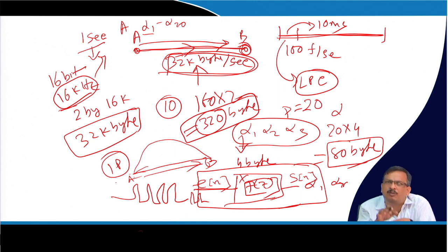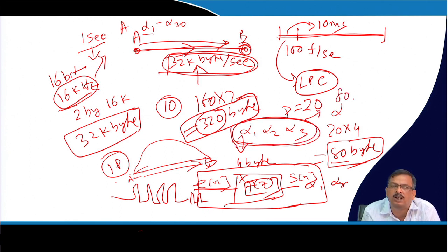Now there will be a lot of complications. There is F0, there will be a gain, there will be impulse position, to make it more generalized, or you can say more natural sounding voice at s(n). There will be a lot of drawbacks due to this design. Those design constraints can be improved by increasing the size. Instead of only transmitting alpha 1, alpha 2, alpha 3, I can transmit along with it the F0 value, the gain value, and whether it is voiced or unvoiced. So I can get back all that information, design the LPC synthesis, and get back the data.